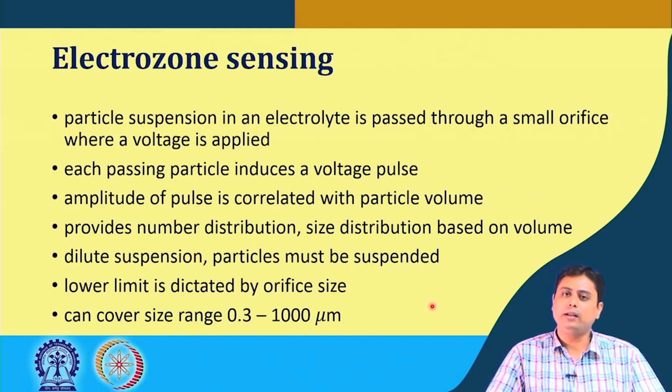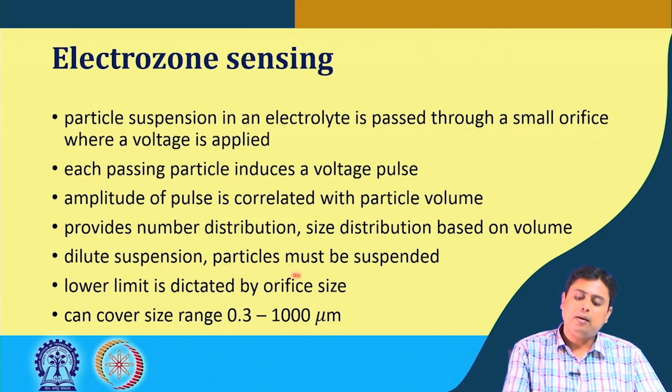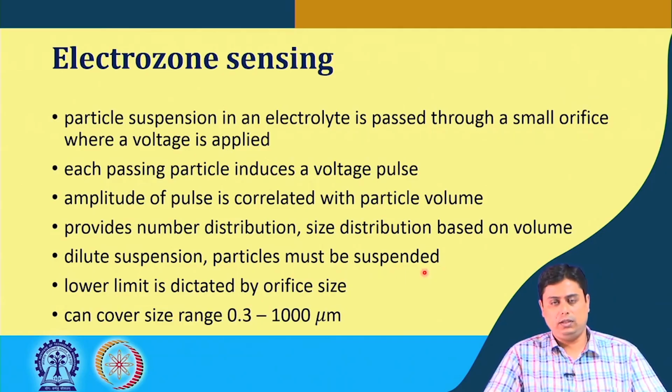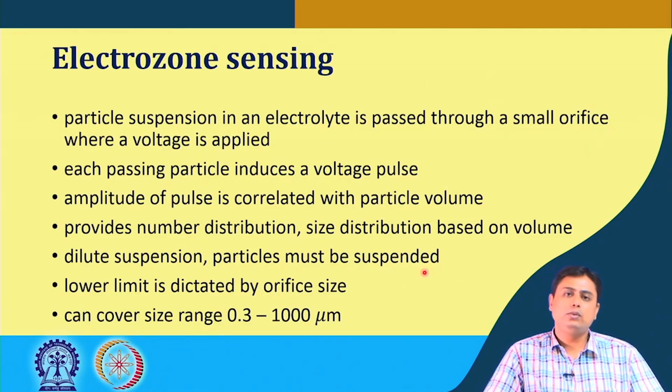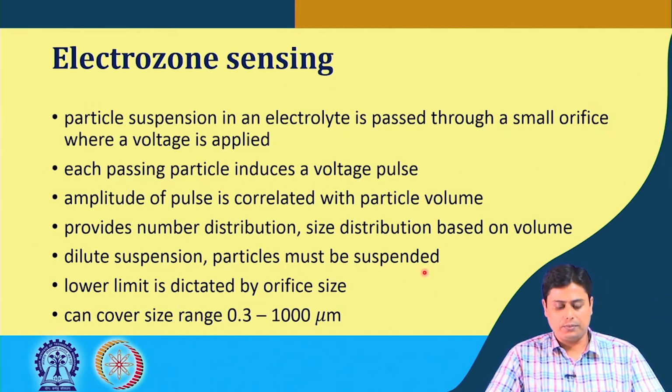The upper limit is dictated by the criterion, as I mentioned, that the particle must be suspended. If it is a bigger particle, it tries to settle down. So, you have to change the suspending fluid media. You have to take a more viscous fluid, so that it can be suspended for a longer time until you withdraw it through the orifice.